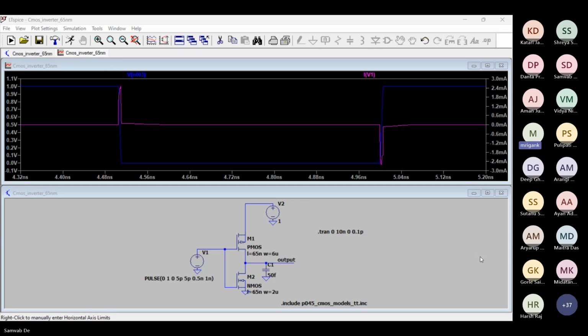In an actual circuit, ultimately all these V1, V2 will be coming from VDD, because assume that this V1 is getting replaced by another inverter. Suppose there is another inverter before this first inverter that you have drawn. You replace V1 by another inverter. Ultimately, the second inverter will be driven by the first inverter, so that inverter is now playing the role of V1. For that inverter, it has to supply a larger capacitor, because this second inverter will be providing a load capacitor to the first inverter, and now it is charging and discharging a bigger capacitor effectively when you increase M1 and M2.